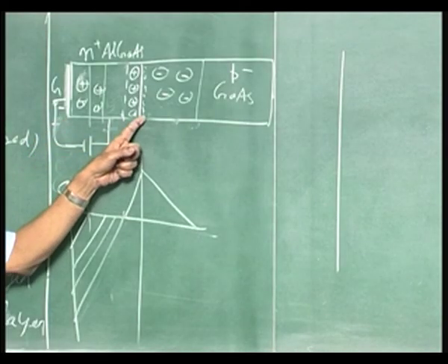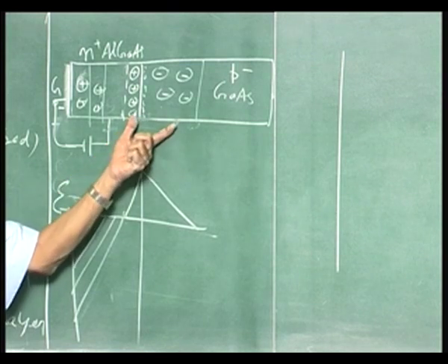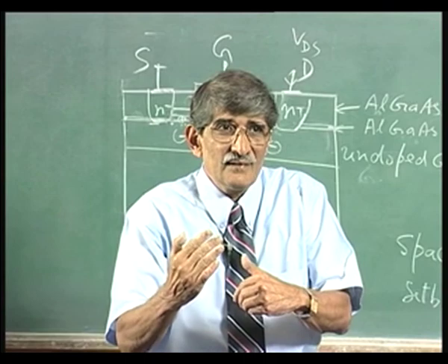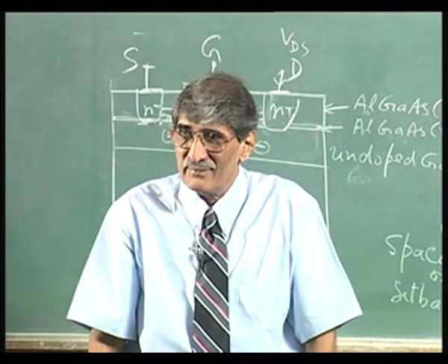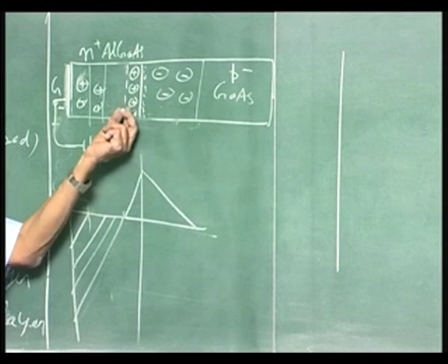When you remove that charge, automatically what happens? Potential barrier lowers. See, the charge, the amount you remove, it is possible only by lowering the potential barrier, which means the depletion layer collapses. If the depletion layer here collapses, what happens to depletion layer here? Collapses.